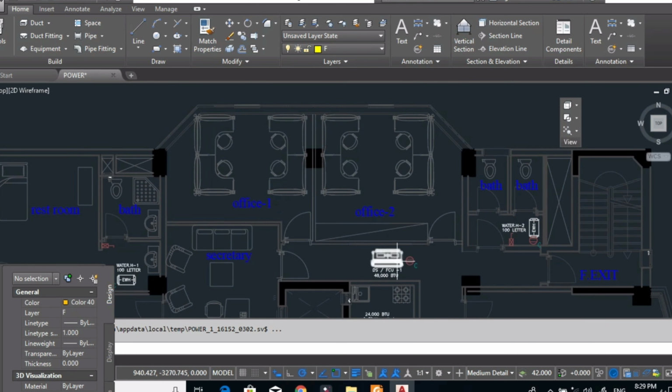For me, I will not put a disconnect switch there because maybe the operator will be confused operating the air conditioning, but I will put one only for these two units, the cassette unit and the split unit. I will put for them here a disconnect switch 45 ampere. It is optional. You can also put a disconnect switch for all the duct split types.